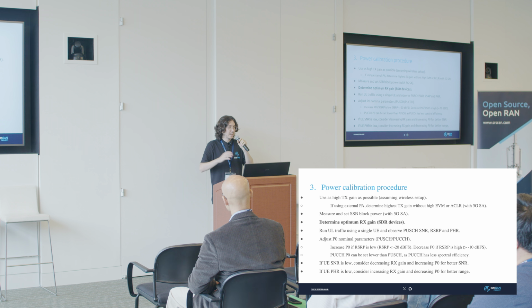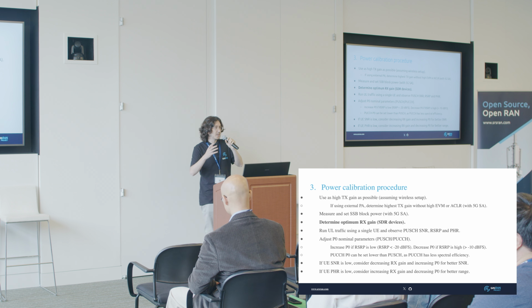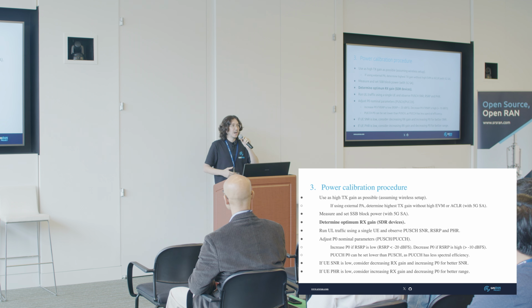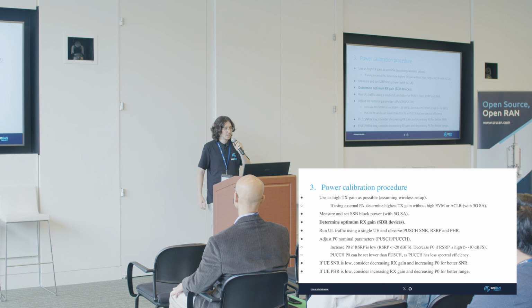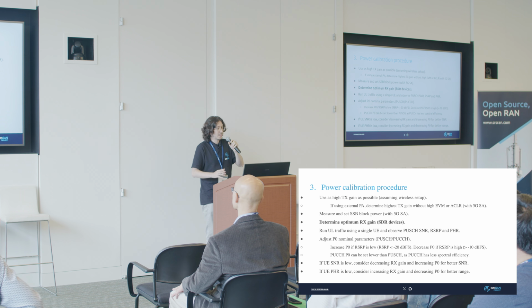One thing is that it will degrade the signal, so the information that is being carried by the signal is affected, and it is not going to be so easy to decode in the receiver. And the other problem is that you will transmit out of band, and then you could be going over the spectrum emissions mask that is a requirement for a specific band that you can transmit on. So again, this is something that needs to be measured, and yeah, that's it.